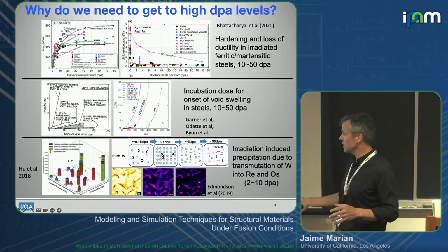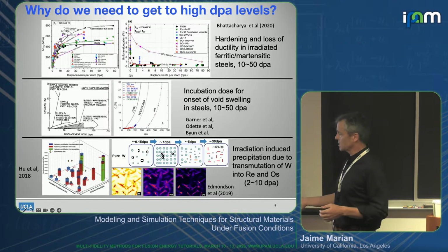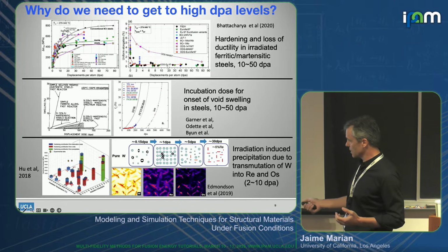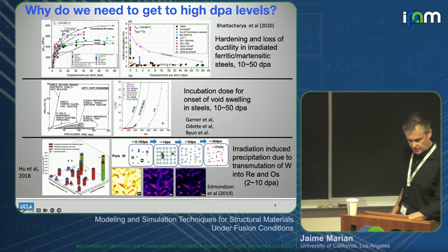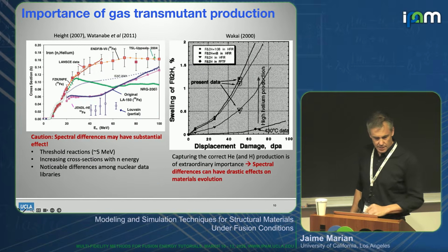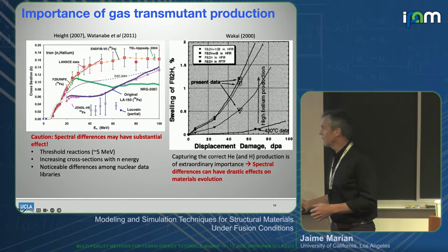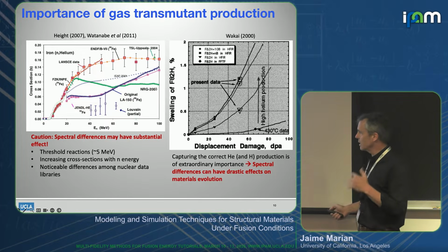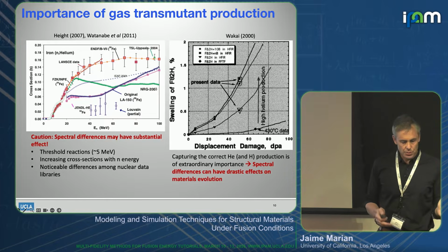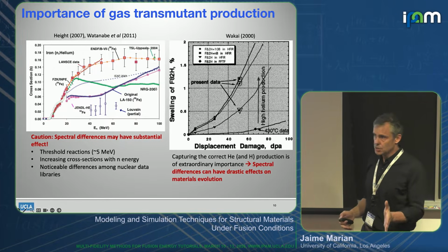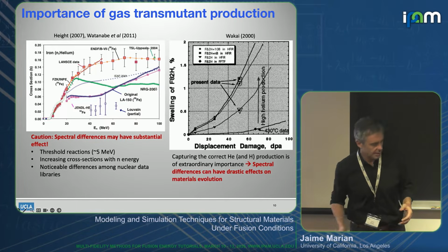We can't sometimes use these theories, standard thermodynamic theories, because they don't apply. But we see their effects in the microstructure of real materials. And again, it brings a whole bunch of issues with it. A huge issue for fusion, which sometimes I think is not fully appreciated, is that almost in every material, you will produce relatively large amounts of hydrogen and helium through transmutation, okay? Alpha particles and protons.